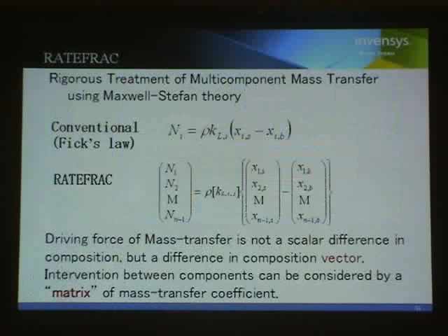RateFrac uses rigorous treatment of multi-component mass transfer using a Maxwell-Stefan approach. In the conventional fixed efficiency approach, the driving force at the interface is described by the difference between compositions of a single component.